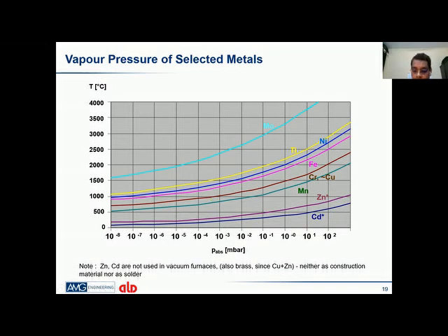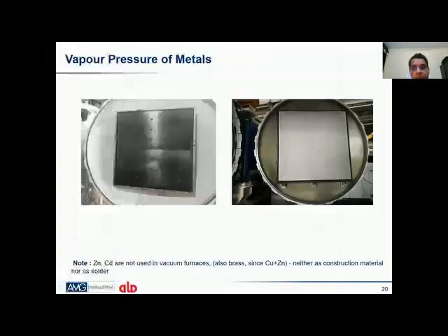and start getting deposited on the furnace. So this is another picture. Initially it was all graphite insulation, black and shiny. When you start putting chromium parts and stainless steel parts, sometimes you see all the shields have become a little bit dusky, with a mirror-like finish. Most of the time we feel we are getting the parts in good quality, but somehow this is not giving a good feeling. We think my furnace is getting discolored, or the gas is not good. But this is nothing but the chromium deposition which happens with most of the parts.